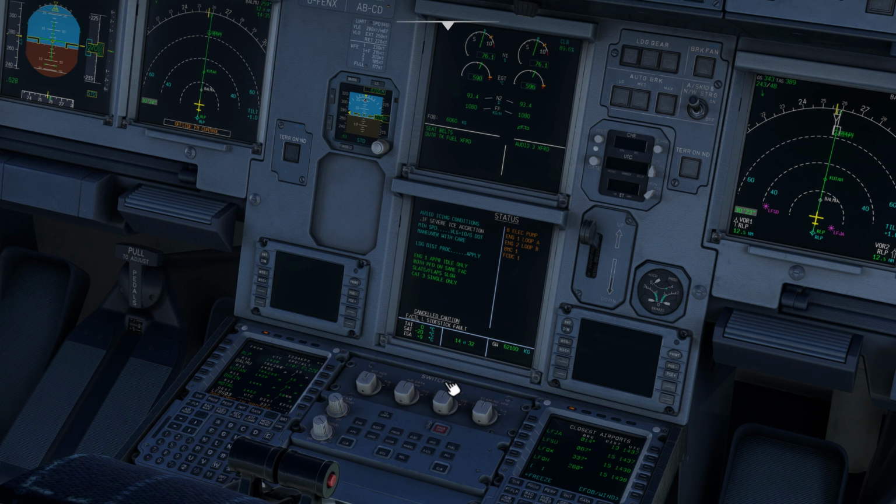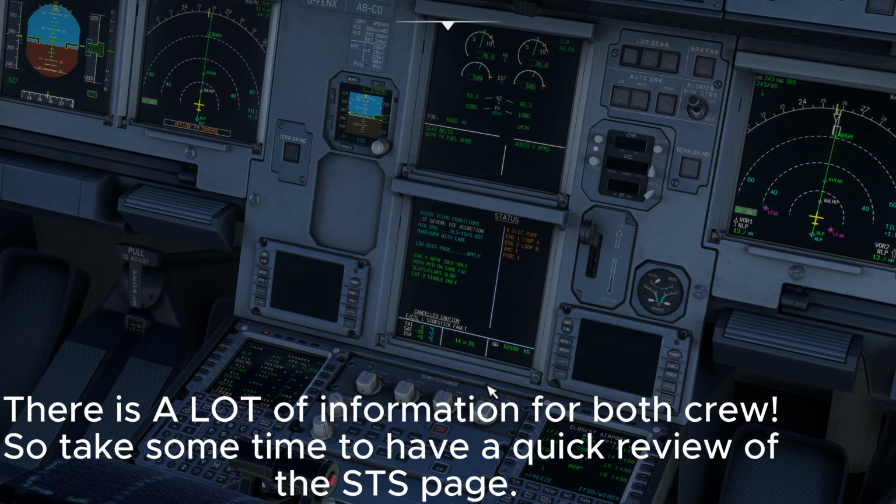Second page inoperative systems are blue ELEC pump, engine 1 loop A, engine 2 loop B, lead monitoring computer 1, and FCDC 1. Remove status? Before you do, let's have a quick review of the important systems that have gone, and what we have left.